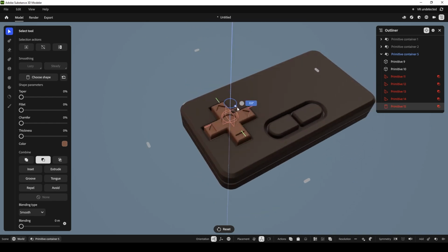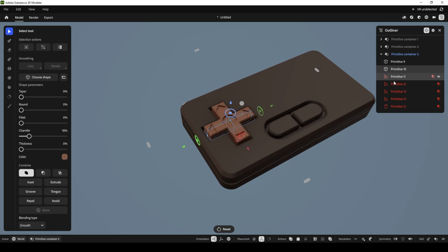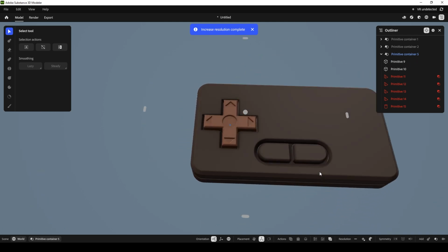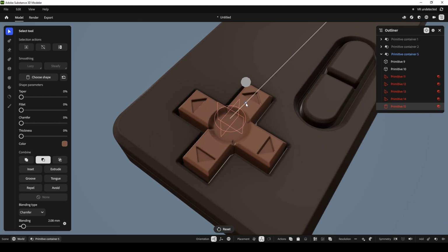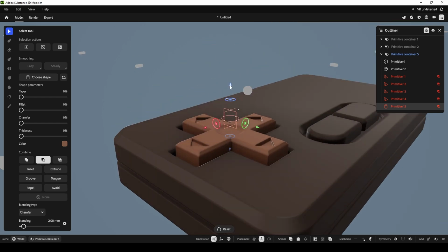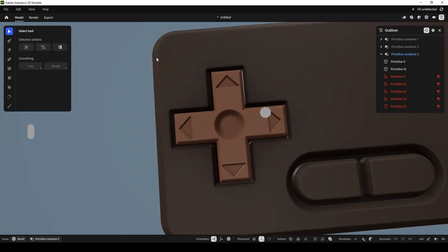And yeah, we've got a nice sort of shape. Whoops, rotating that. I want to grab that one. Got a nice shape there. And then we've got a bunch of different shapes here. Again, let's up the resolution there, make those cuts nice and sharp. And with this, maybe we want to chamfer that edge a little bit as well, so you can see where the chamfer is coming out, so you can do quite interesting features with it. Maybe we want to scale that a little bit more because of the chamfer. And then we've got a nice shape quite quickly in there.